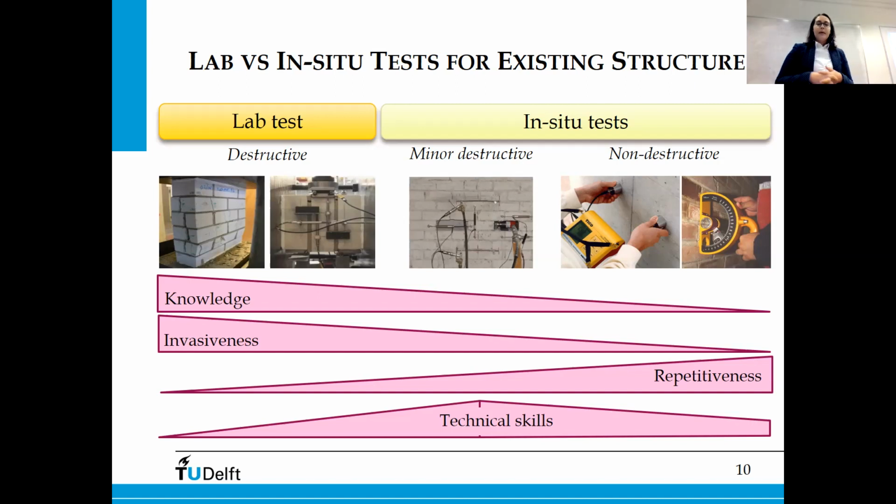Well, we tried in our lab, but the question was, okay, if we had a wall that was only double width, and we had to cut a slot to enter this flat jack, then actually this was very difficult already, to find the eccentric saw to make this cut, because there was only one in Amsterdam to be rented. So this is an example to say how, when a technique is not there, it's not so easy and fast to implement it.